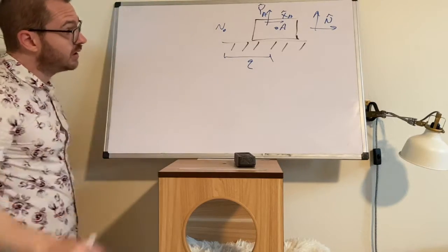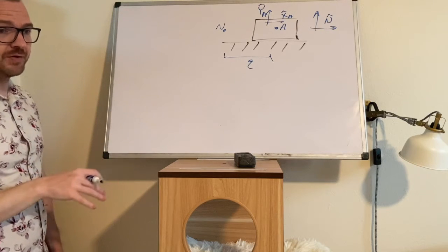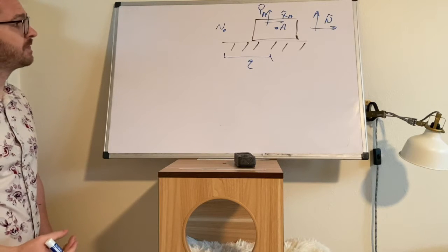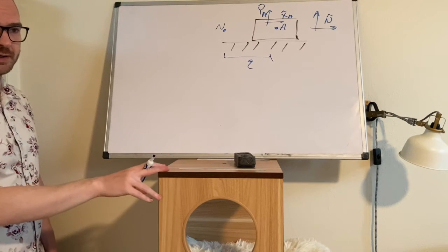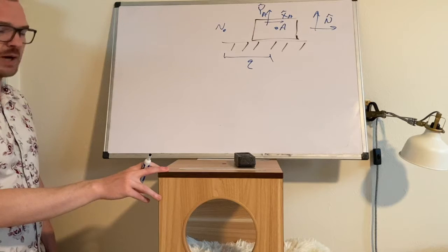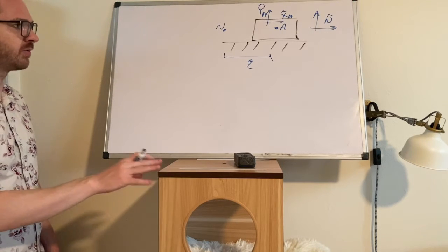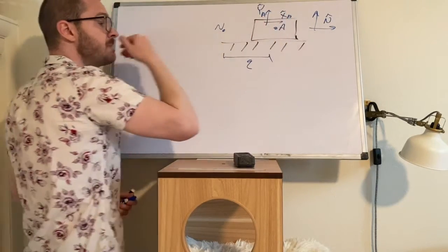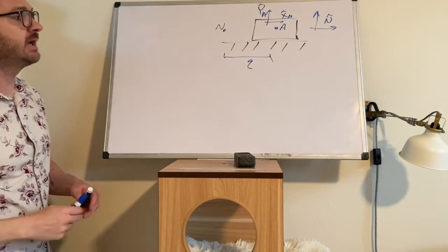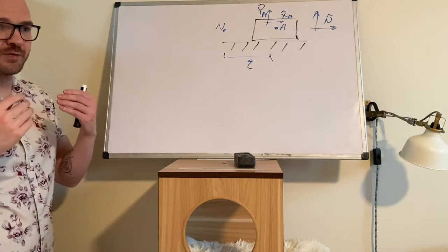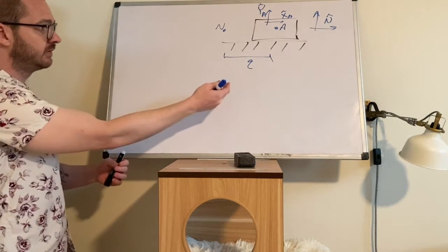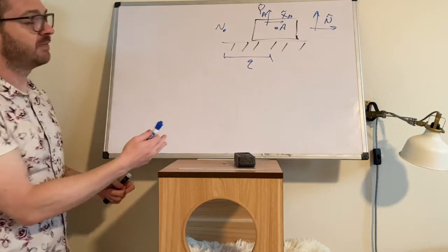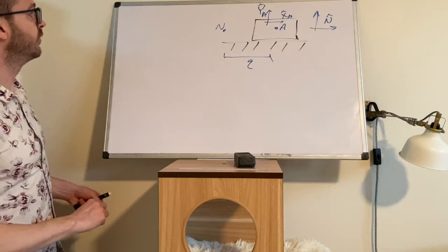Okay, so we have the write-up for this problem. You have it all in your notes. We want to discuss the velocity of this problem. And remember, we have two types, angular and linear. My advice is to actually do angular first. Most problems, especially problems where you're doing simple rotations, the angular velocity you can usually just write down from observation. Just look at this thing and you can tell how it's rotating. In this problem, it's not rotating. So what do we need to do?